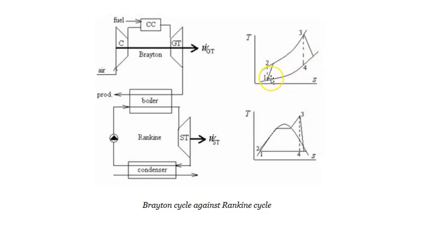This temperature here on this diagram will be very similar to this temperature here on this diagram. So if you overlaid these, we can utilize that process in this cycle. So as said before, a combined cycle is 2 or more systems operating at different temperatures and sometimes different fluids.